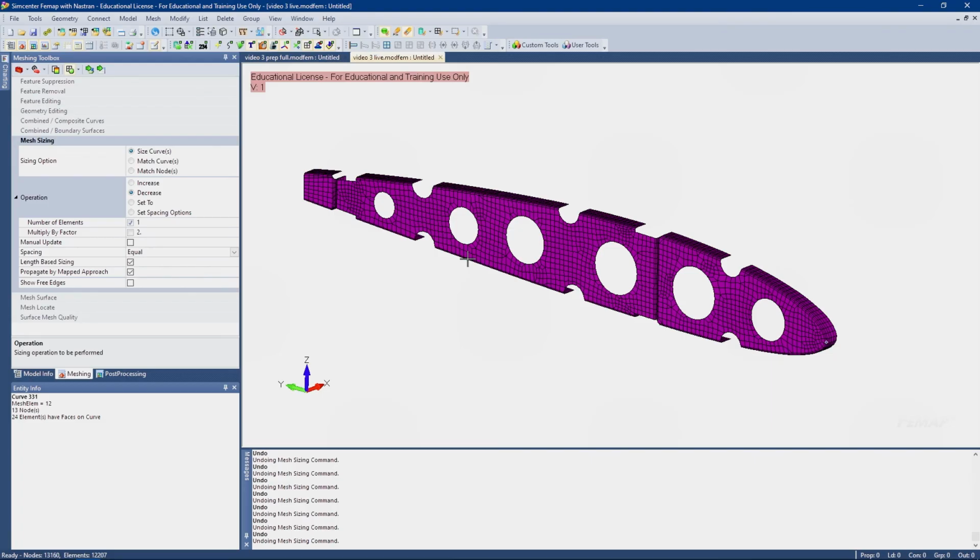There are a bunch of techniques which perhaps I'll do a video on in the future about how to spend a bit of extra time and get a really great mesh for fairly complex geometry, and a lot of times it comes down to, before you're even in FEMAP, masking out your surfaces and essentially trying to guide the elements into uniform shapes.